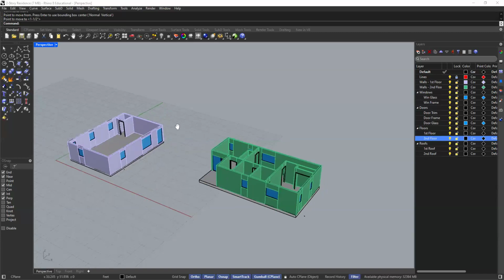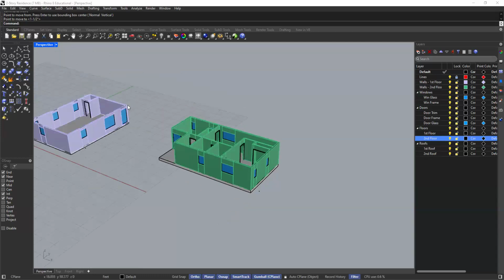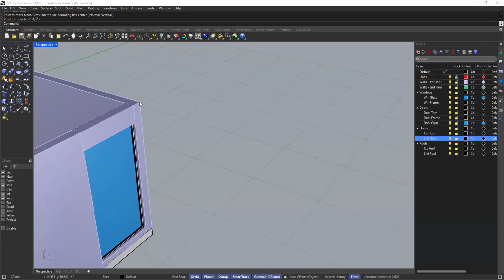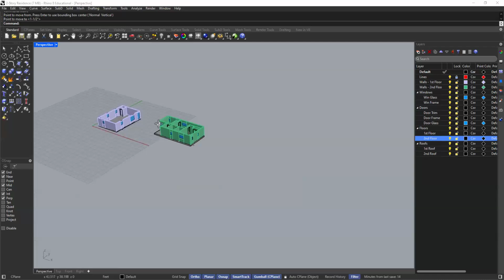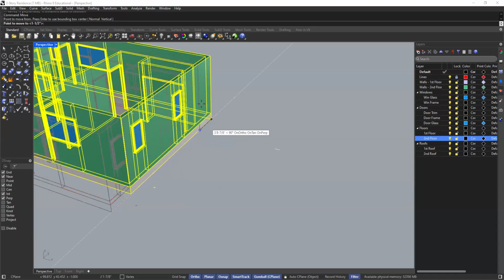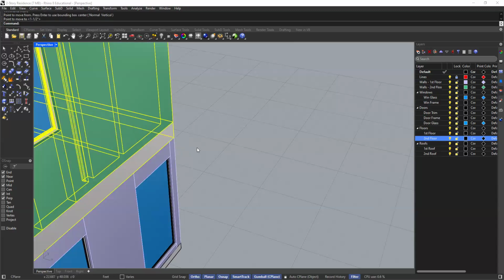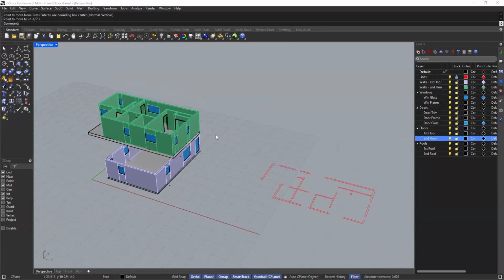But if I say, well, technically, this corner here should line up to that corner right there, so now that I know that, then I'll go ahead and select the move. So I'll go move, and I'll grab the object from this corner here. And now I know exactly where these two should line up, and I'll click, and there we go.